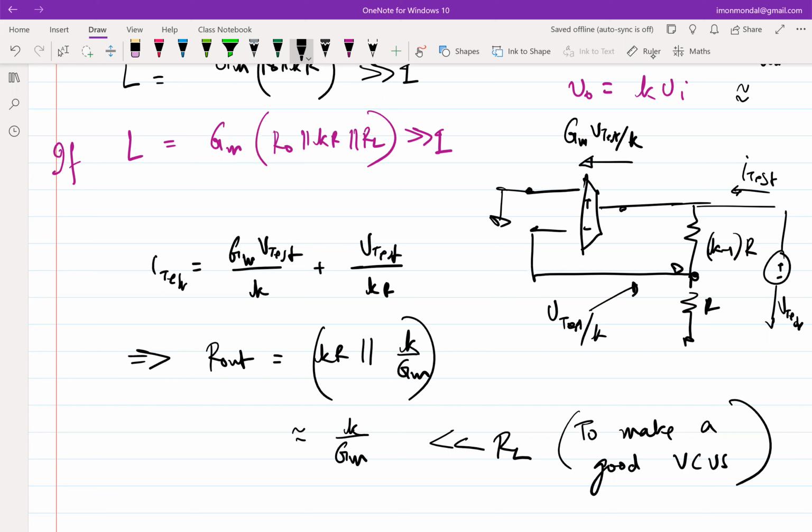And how is it doing that? If you analyze this contraption from the perspective of output impedance, you apply something at the output, right? You excite the output voltage. Part of that output voltage comes and kicks the error amplifier through the feedback network, and it kicks in a direction that it draws in a large amount of current from the output, and that's how it reduces the output impedance. And without negative feedback, this wouldn't have been possible. Okay, does that make sense?